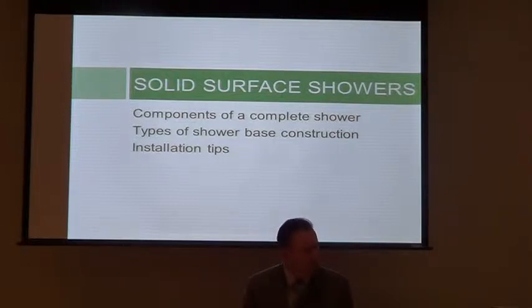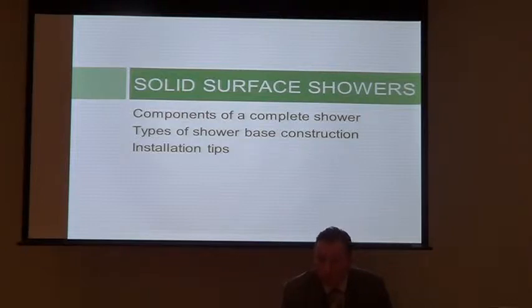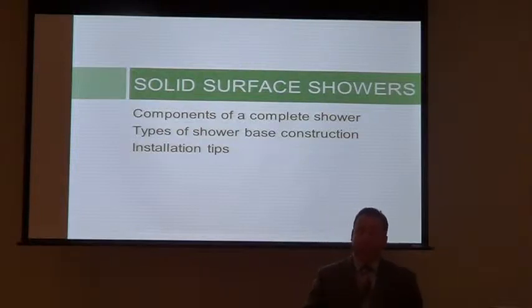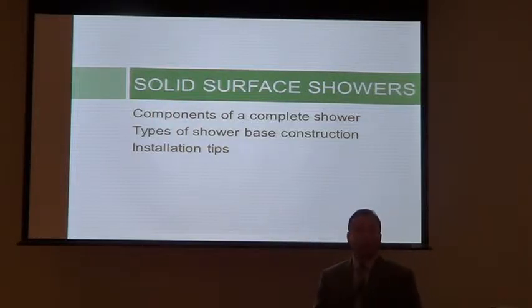Okay, so that might take a little trial and error, but essentially, play with my grades of paper and get it to blend out. If I take my fingers, there's more PSI, pounds per square inch, on my fingertips right now than there was on that sander. And that's where some people can get into trouble. Well, Sean said I can just take some sandpaper and remove that scratch. You will, but if you're using your fingers, you're too aggressive. Okay? So the trade, the industry is well aware of that. They're going to go right to just a simple palm sander and buff it up.